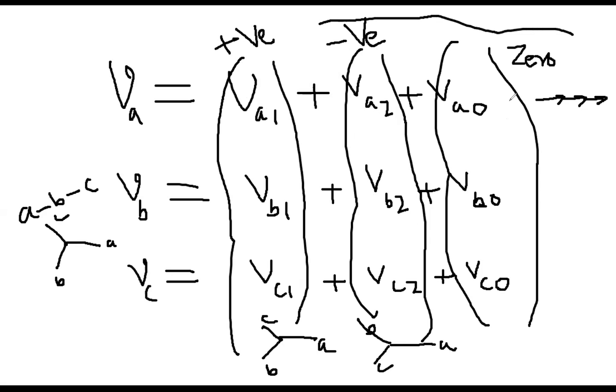These two are not desired components. It was an unbalanced system, that is fine, and this is a three-phase system, A, B, C phase, and I got a positive sequence three-phase system. But what is the meaning of this negative and zero? Those two will have a negative impact on the system. Like that negative sequence, this will cause some sort of heating in the system, and then zero sequence, this will also cause heating, and the zero sequence current will flow through the neutral of the Y connected system.